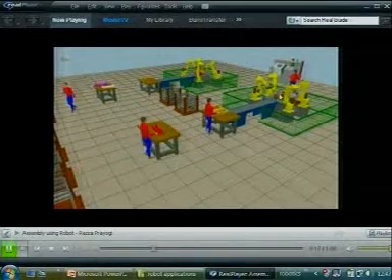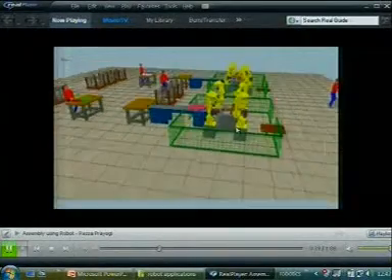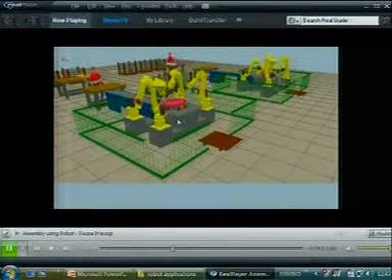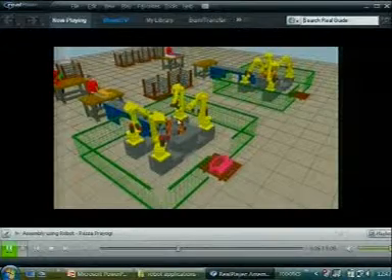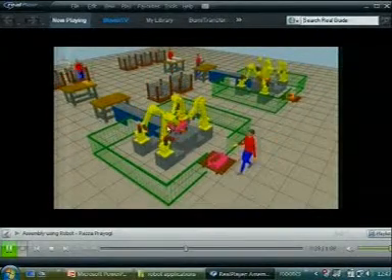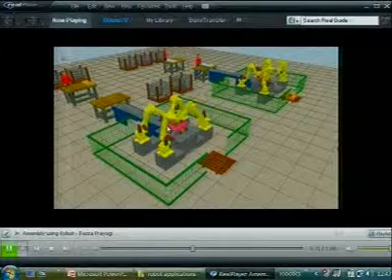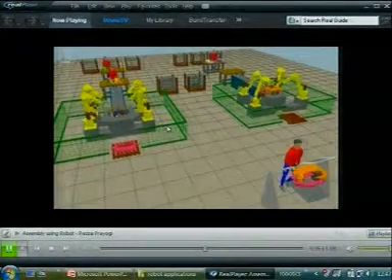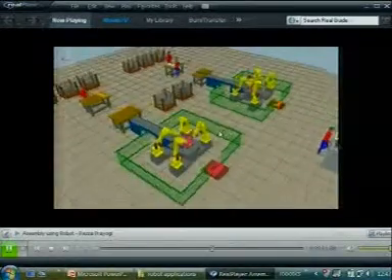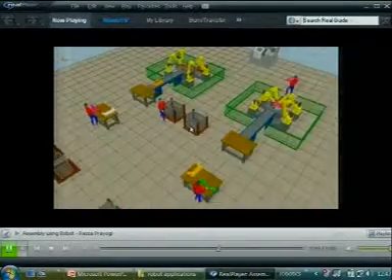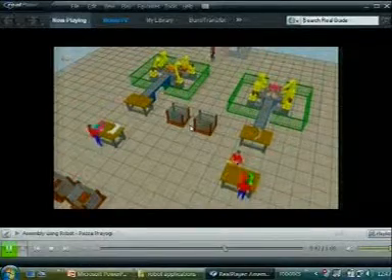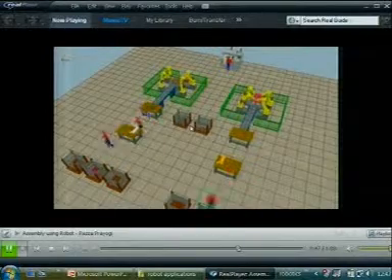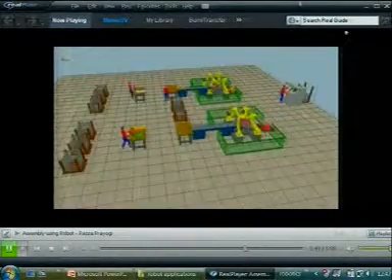So, these movements I can do in my CAD environment the way it is shown here. Once this moves perfectly, I will save these programs and download them to the real robot, and then the real robot will play it back. So, what is happening here is a simulation. This is one type of offline programming, that means programming by simulation, which is the third type that I will be discussing on my slides.